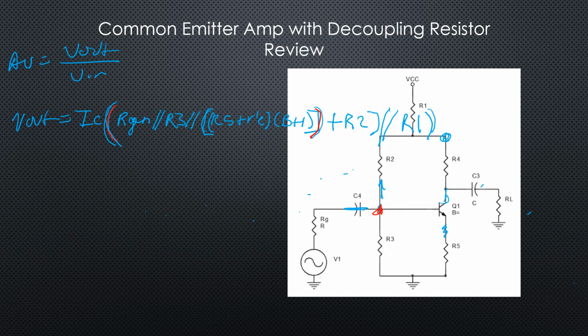All of that is going to be in series with R4, so we're going to add R4. So if you look at the math and try to approximate, you've got R1 plus R4. But you can't really say that without that decoupling capacitor there. But mathematically, that's what it's going to end up being pretty darn close to.